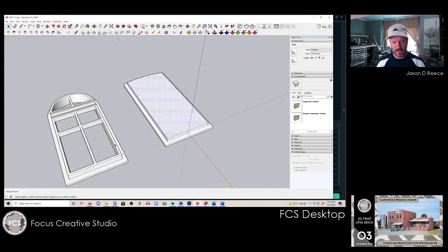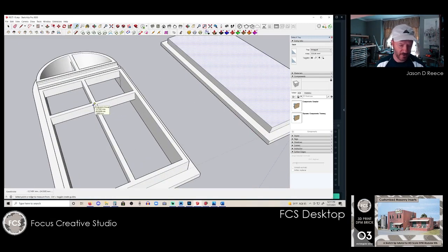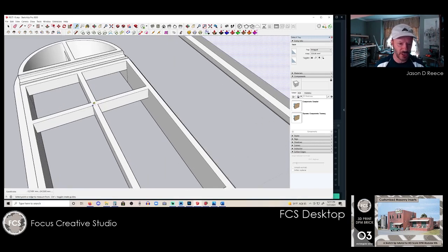series here. And so real quick, these are dimensions for mullions that I have personally decided are perfect for me. Everybody has different means and methods per se when it comes to 3D printing. I know the 3D printing guidelines, what prints well. Can you push the limits? Sure. But my goal is consistent quality prints every time without having to deal with failures over and over and over again. So mullion widths, 0.5 millimeters.